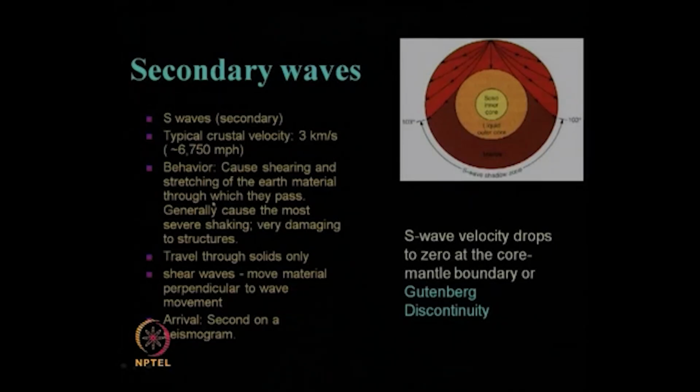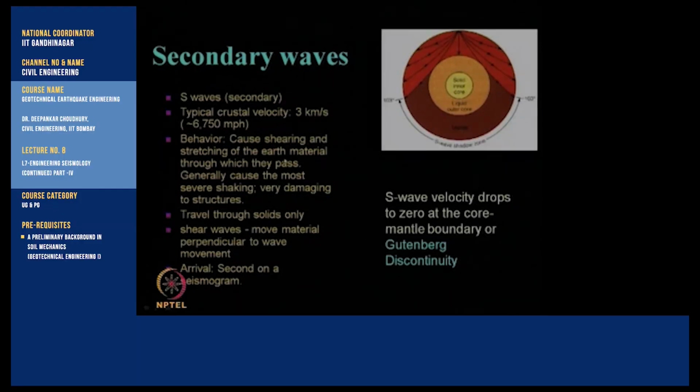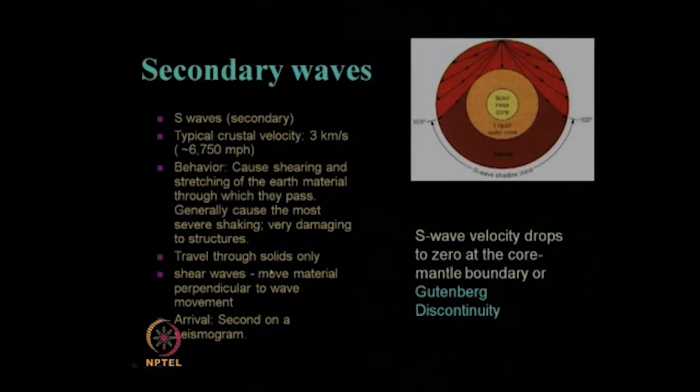And its behavior is, it causes shearing and stretching of the earth's material through which they pass, and generally it causes the most severe shaking, which is very damaging to structures. And shear waves travel through only solid media, they cannot travel through fluid media, that is, they cannot travel through liquid and gaseous media, because they are shear waves.